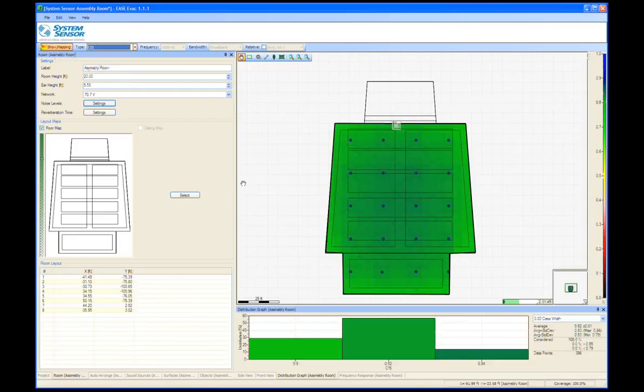Okay. When you were bringing in the background images, the attendee here didn't see PDF. Is PDF an option for importing background images? No, that's a great question. I'm glad they brought it up. I should have covered that. PDF is not an option to import a background image. However, if the only thing you have is a PDF as opposed to an image or a CAD file, you can have that PDF image up on your screen and just do a print screen and save that to a bitmap using Paint or any other image editing program. And then you can open up that bitmap or PNG or JPEG or however you chose to save that file.